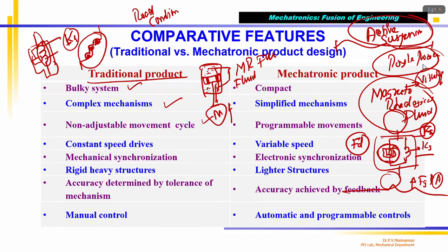That means when the piston goes up, I call this chamber A and this B, the fluid should come from A to B through this hole. The rate at which fluid flows from chamber A to B is going to decide at what rate the piston can move. So there is an opposing force, that is called damping force. The damping force is proportional to the hole size, the orifice diameter D, and also the viscosity of the fluid filled in it. In a conventional damper, you have regular oil where viscosity is fixed. In an MR damper, instead of oil, I will fill it with MR fluid.